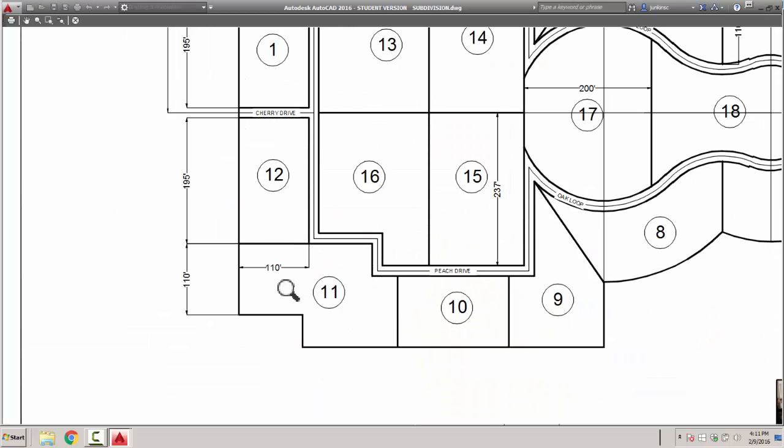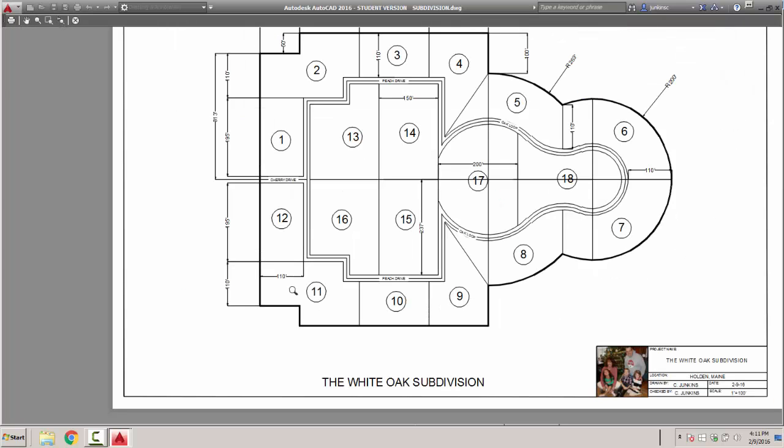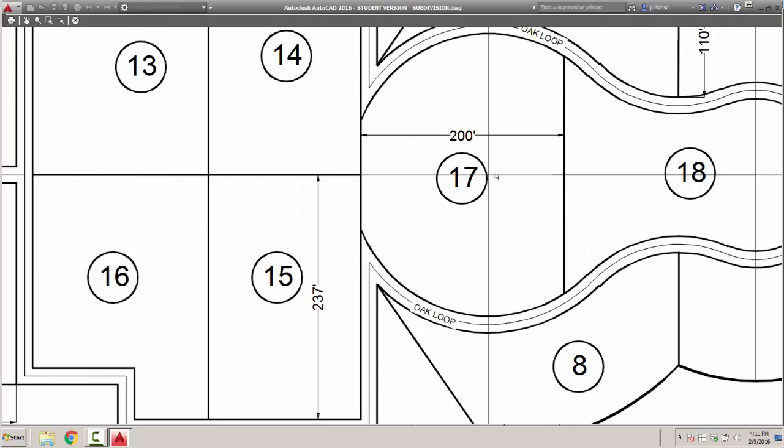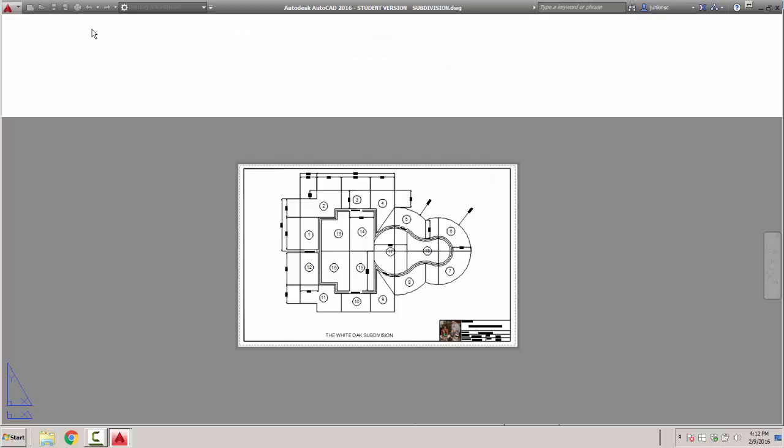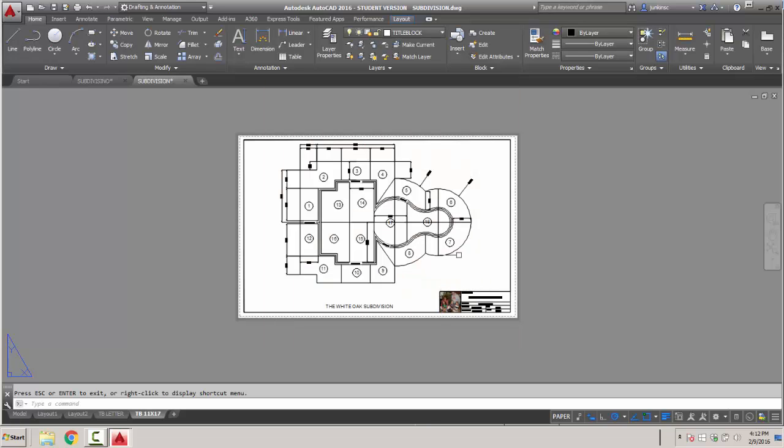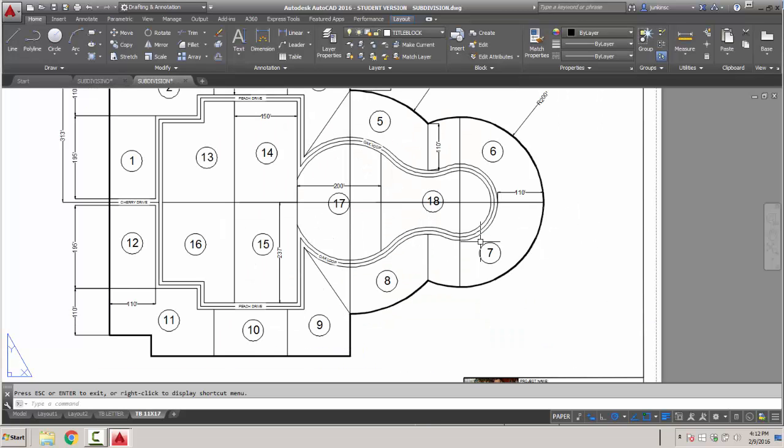And if I want to take a look, make sure my lines are all in good shape. That should show up as a hidden line. So, close that preview window, cancel that. So if I type in, and that center line should be in, I'm going to type LT scale, say 1. Oh, that's why. Because it was making it 400 of the actual, so just call it 1. LT scale 1 on your viewport.